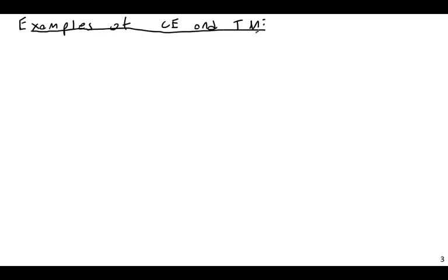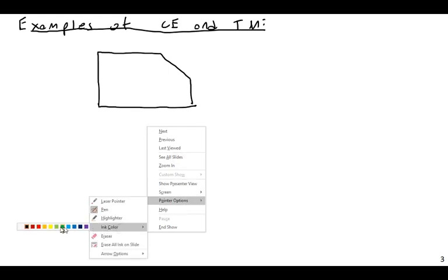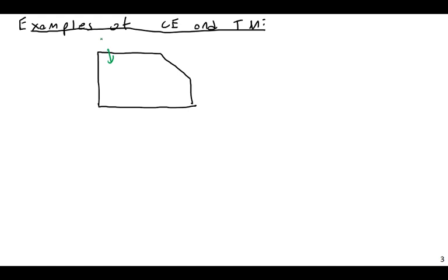Two examples I wish to describe are gusset plates and splice plates. So you might have a gusset plate. A gusset plate is simply a plate, a flat piece of steel, that is used to connect various tension members or other members. It's very common to see these, especially in places like trusses. If you ever see something like this, a plate where several tension members come together, that is an example of a gusset plate. So again, this is a gusset plate.